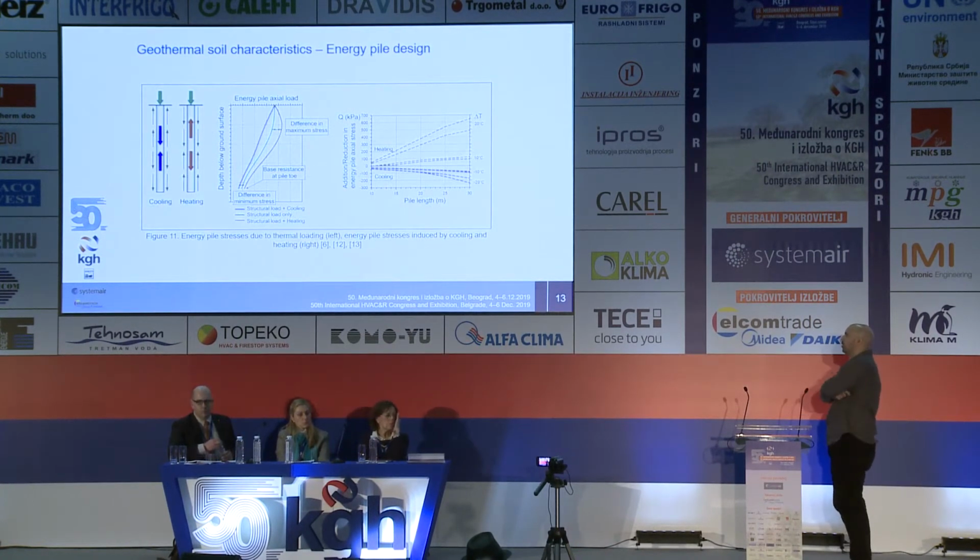So, one of the effects of the cooling load is shrinkage of the element, and the effect of the heating load is the expansion of the element. If we apply that for a long time with cyclic loads and changes in the temperature, it eventually can harm the element or the elements, if you want.